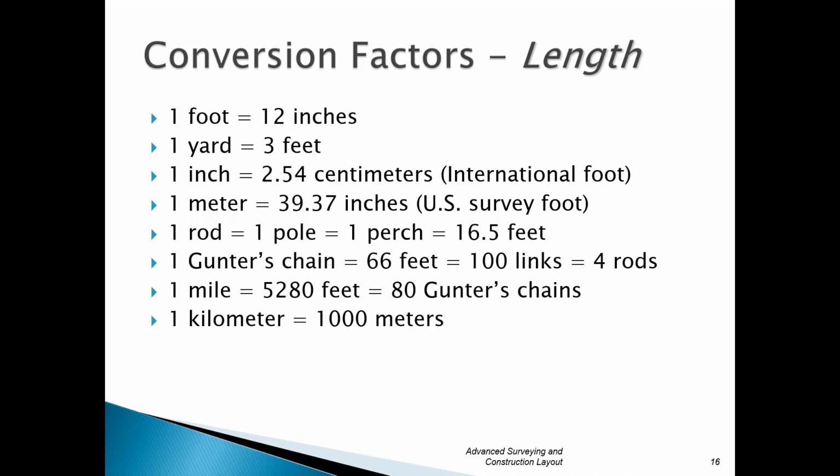Michigan is international feet. So if you're using a total station and your total station is set to U.S. survey feet and you're in Michigan, you're going to have mistakes when you start measuring stuff. Now, they're small, they're parts per million, but when you start shooting those distances out miles, then it starts to make a difference. So we'll talk about that a lot more as we get into this on Thursday.